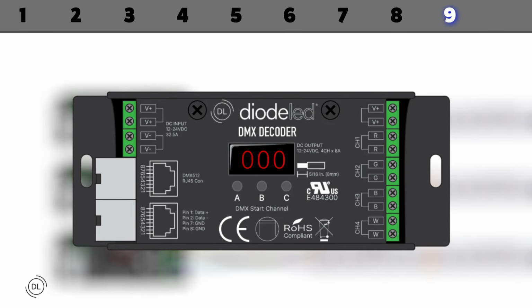For this example, since we are using addresses 001, 005, and 009, we only need to press the third button. Using higher values will be project-specific. To reset the DMX decoder, you hold the first and third buttons together for 3 seconds, where the decoder display and fixture will flash. Once an address is selected for your fixture, the remaining 3 channels will be utilized digitally.